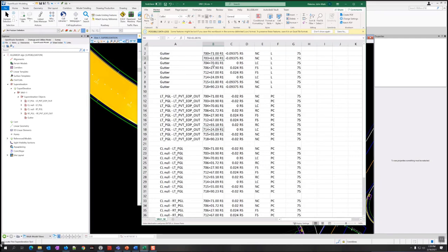But this one is too long of a transition for the gutter, because the gutters are just going to be 0.09375 theoretically until you hit 0. We need to transition it because you don't just jump from 0.09375 to 0. You should transition, but it only needs a transition over a few feet. This is really up to you, but I just said 10 feet sounds reasonable. If you think it's not, that's your project, and there's no standard on that I can tell. If you find something, let us know and we'll put it in, but I haven't found any standard. Standard plans just says the gutter needs to follow it on the high side, and that's all we're trying to do here.